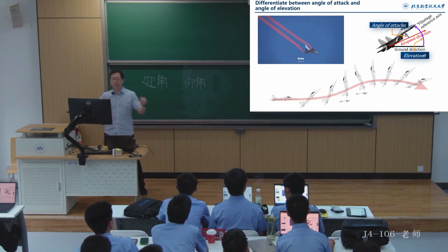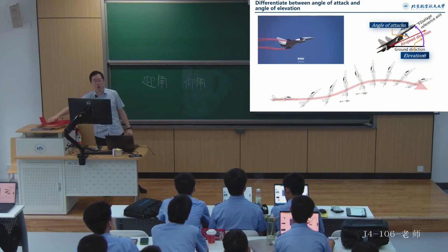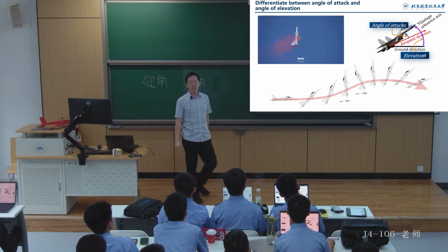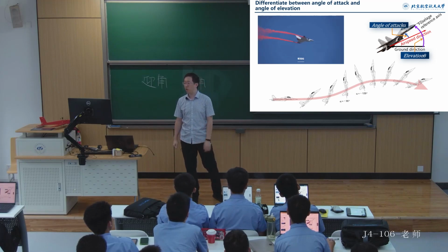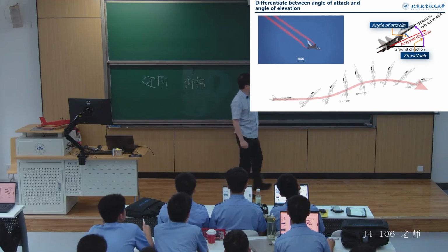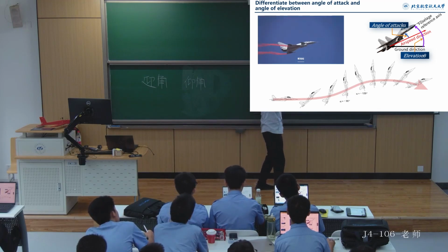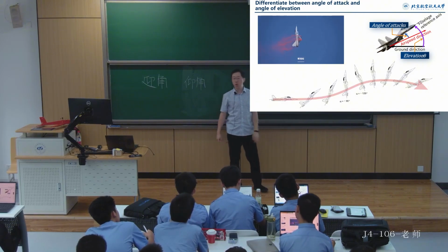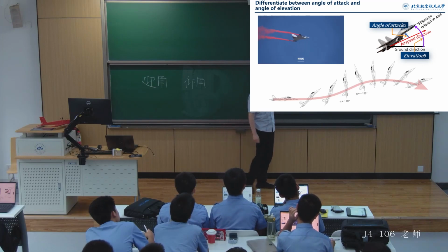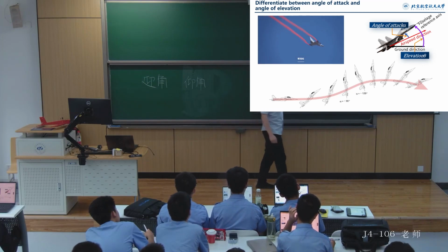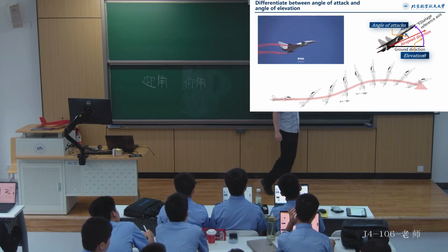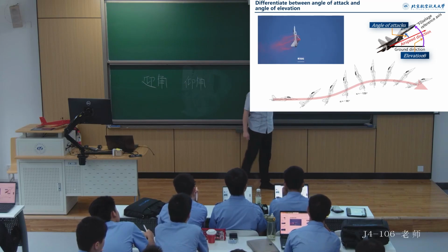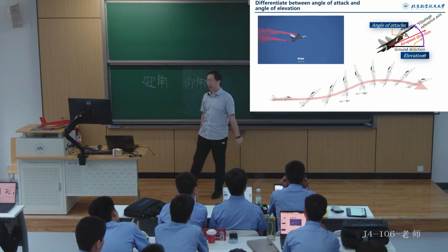So, what is this Pugachev's Cobra maneuver? During its flight process, it actually involves both a high angle of attack and a high pitch angle simultaneously, right? The large angle of attack occurs because once the aircraft is upright, there is a significant angle between it and the direction of the airflow. This angle can reach approximately 110 to 120 degrees. The pitch angle refers to the angle between the aircraft's body axis and the horizontal plane once it is upright, which is also substantial. In this situation of approximately 110 degrees, and during this maneuvering process, the angle of attack and the pitch angle are roughly the same.